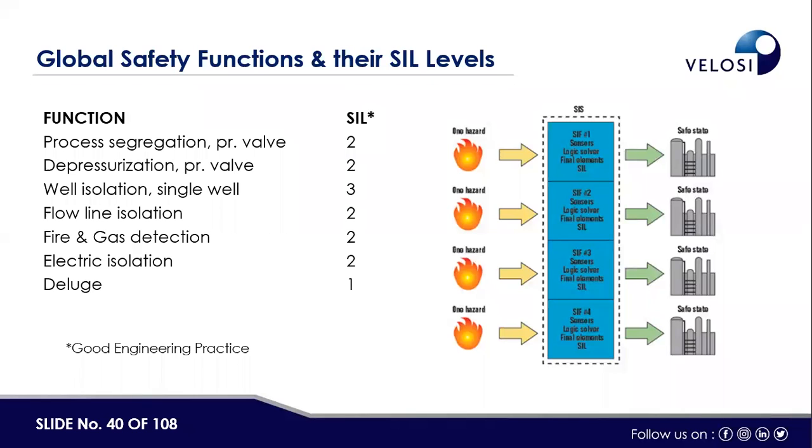So it means at the operational phase as well, even the operational teams or instrumentation and control teams working from the client side or operator side may try to reduce the SIL targets, and in that scenario they will end up reducing their workload. So there is a conflict of interest on both sides.